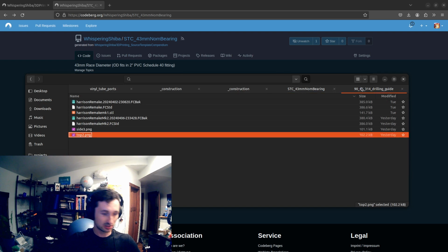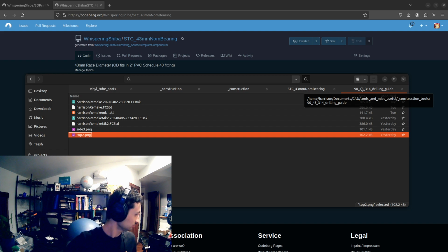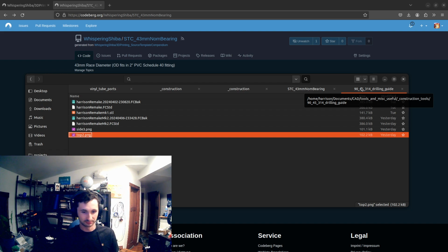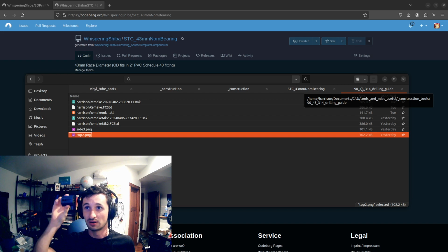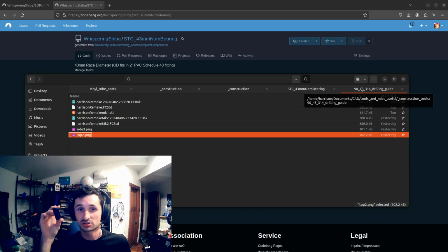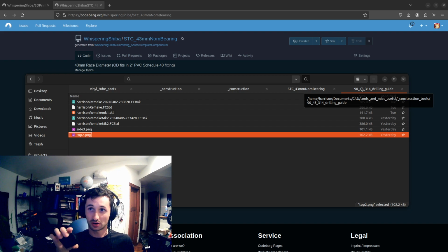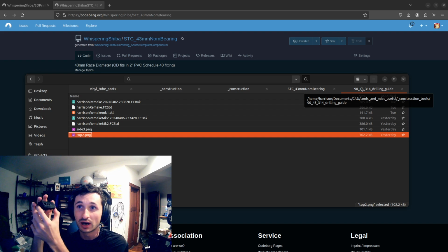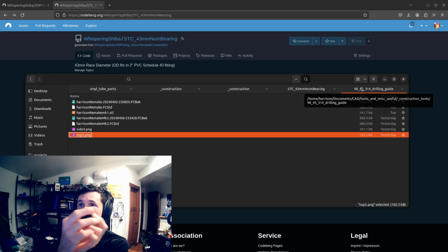project, right? So I have this drill guide. I placed it somewhere right here. I derived this off of somebody else's design. It has a bunch of holes to help you drill. But what I noticed is with a number 9, 2.5 inch construction screw, if I use the 45-degree angle drill guide, which is on this face, the tip of the screw goes through.